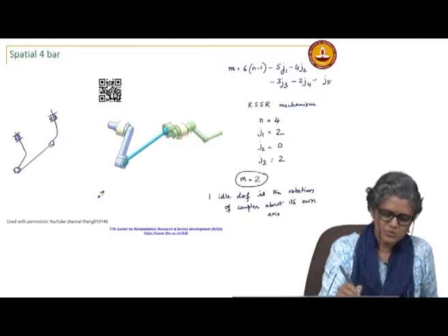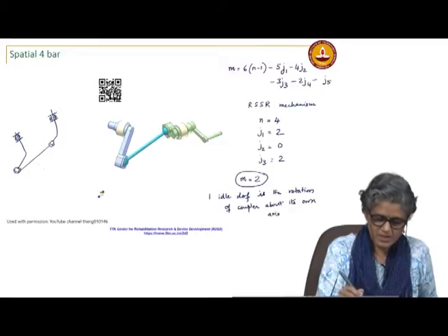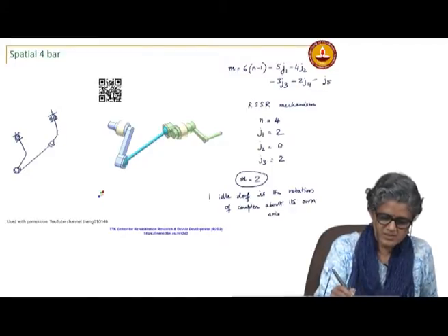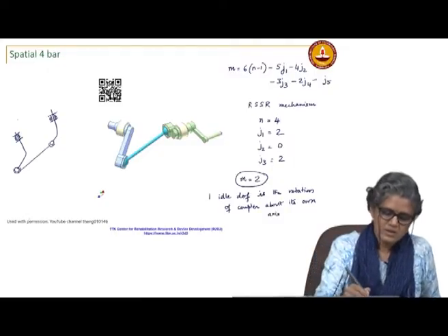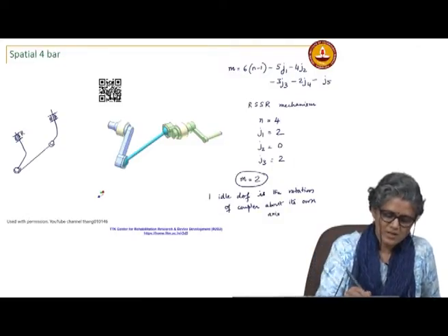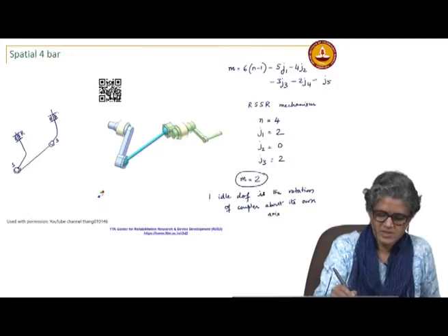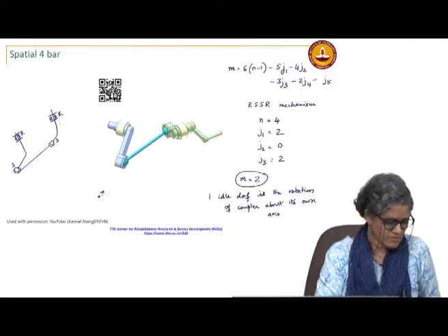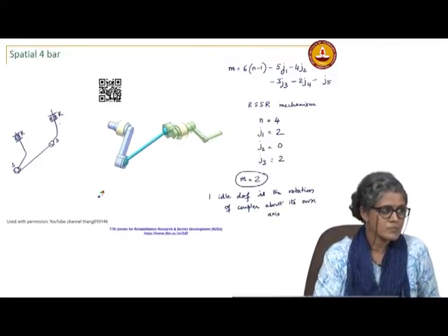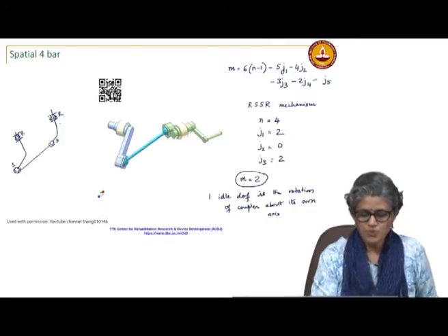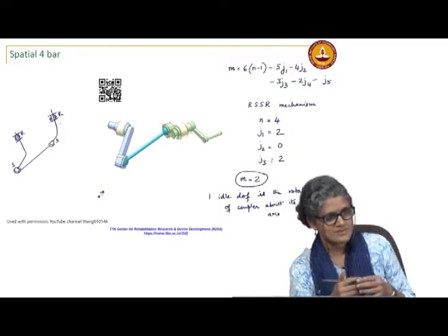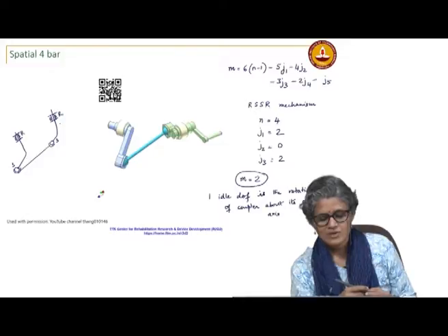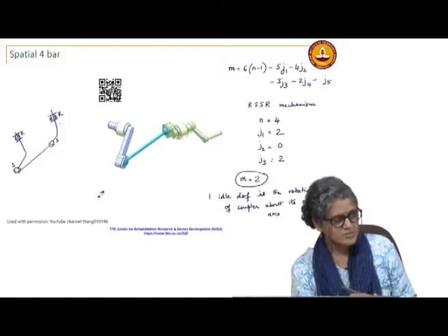So, this could be moving in a circle like this and this. So, you would have your R, S, S, R. So even for these 4 bar, are there 2 linkages, a cross version and a straight version? Depends on what you define as cross and straight here, right? Everything is, so this also has multiple branches. It could have multiple branches, yeah.